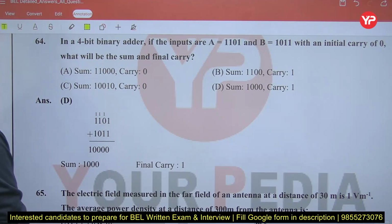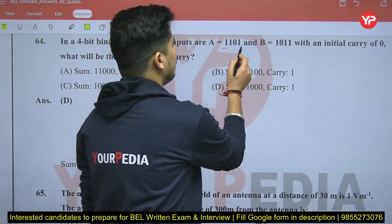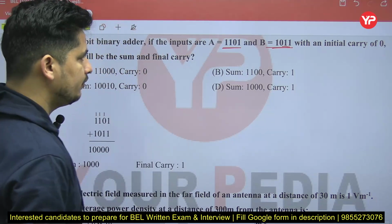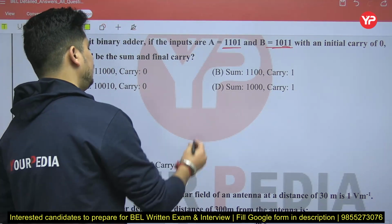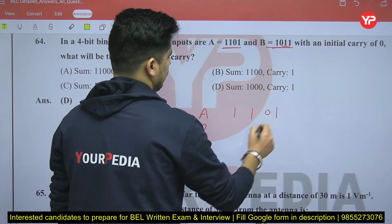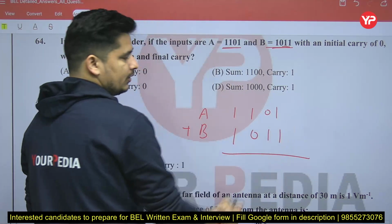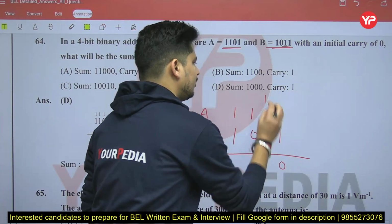In a 4-bit binary adder, if the input A is 1101 and B is 1011 with internal carry 0, what will be the sum and final carry? Basically, when we add A plus B, it is 1101 plus 1011. So when you add 1 and 1 that becomes 0, with 1 carry here.